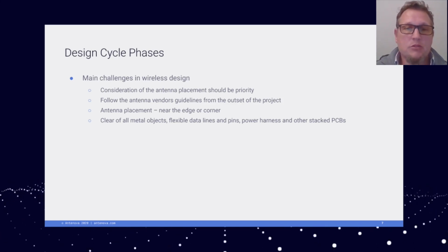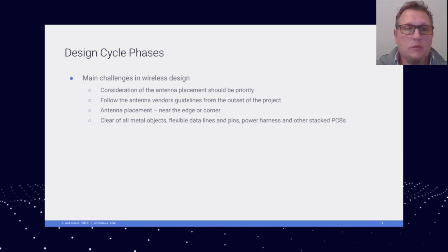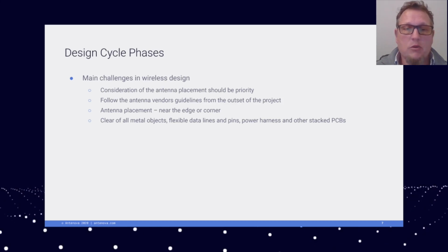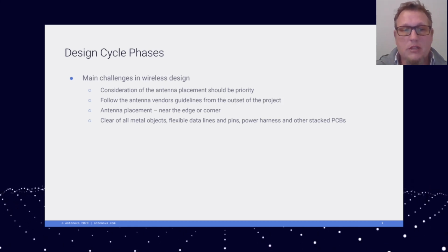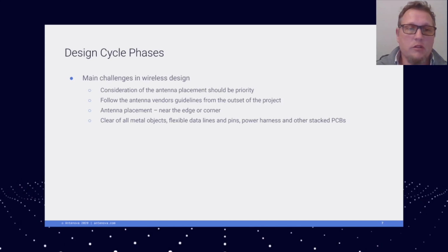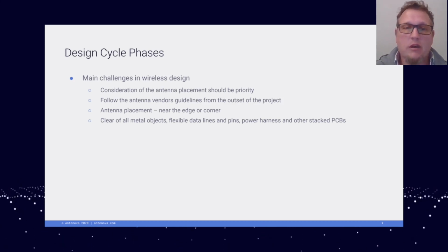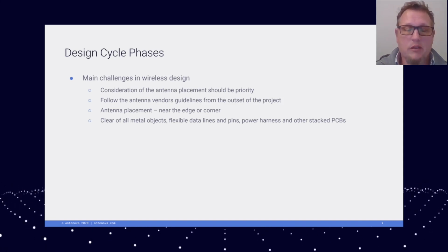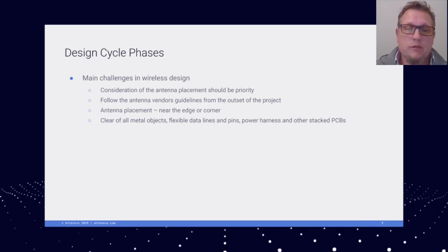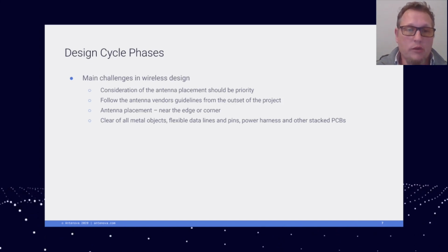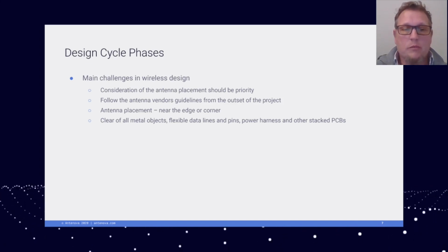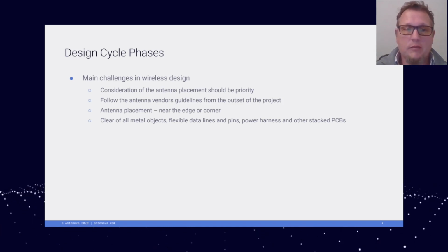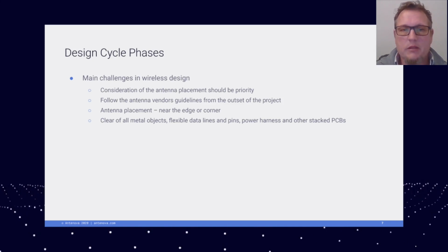Antenna placement is also something to consider. The printed circuit boards can get pretty densely populated, so certain antennas can function better along the long edge of the PCB. Others will like to take up the end of the short length of your PCB, and others function fairly well near the corner of your device. So the antenna position is critical, but can be manipulated.